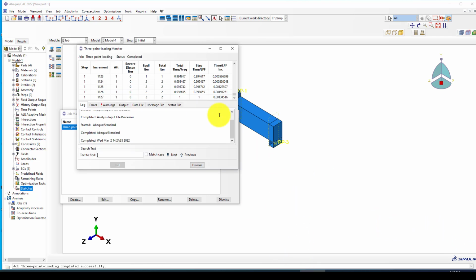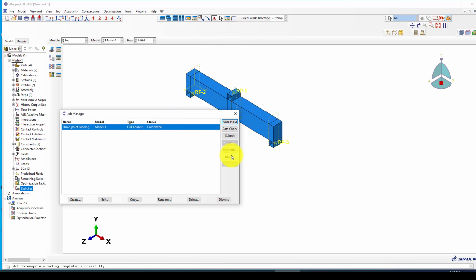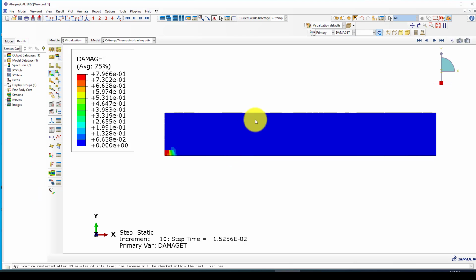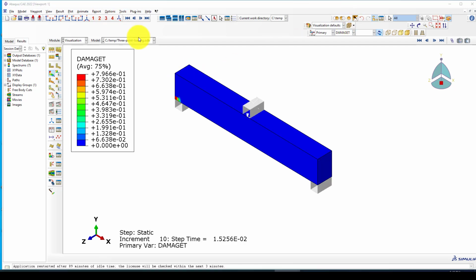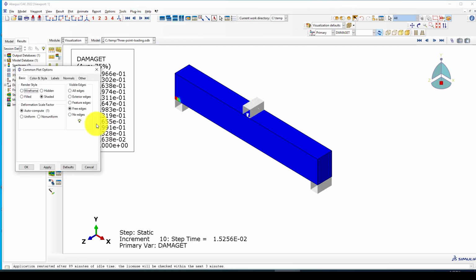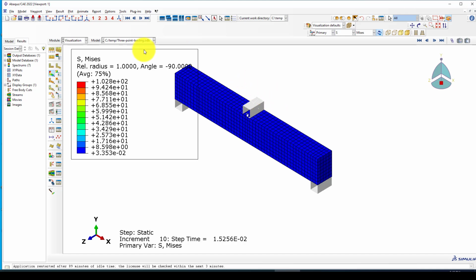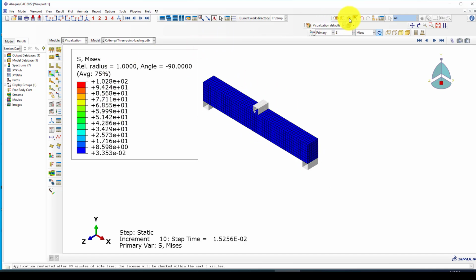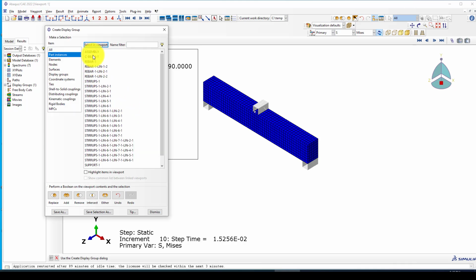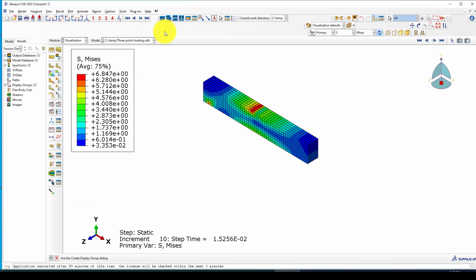After a few hours, it's completed, and it took about 1100 steps. And now I go to result. And this is the result. Now it's showing just the concrete damage, and we want to see the stress strain. It includes the rebar. We want to remove the rebar. This is the concrete beam replace, and you can see.